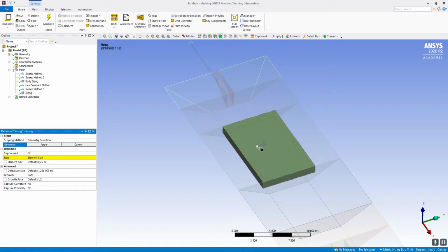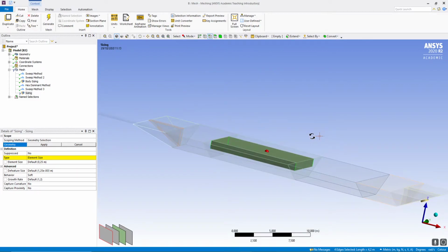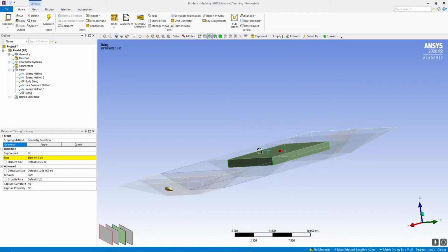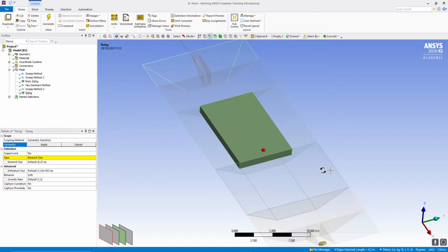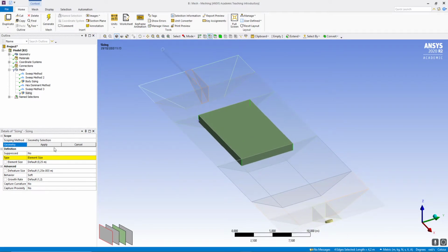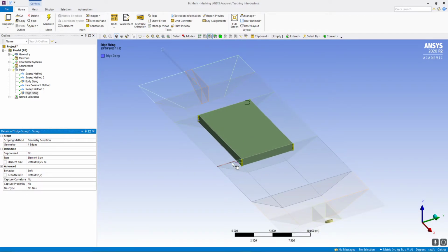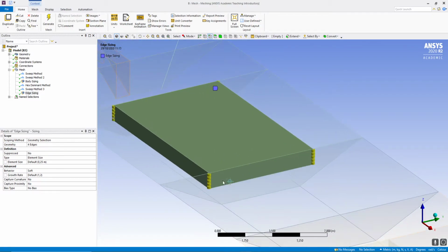All right, so how do we do this? You go here and select the edge command, and hold Control and select that edge, this one, the one in the back, and this one. So you can see that I selected the 4 edges of our rectangle that will represent the vegetation. Okay, and you can click apply.